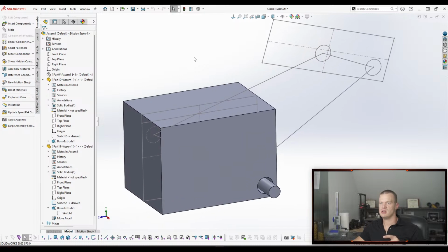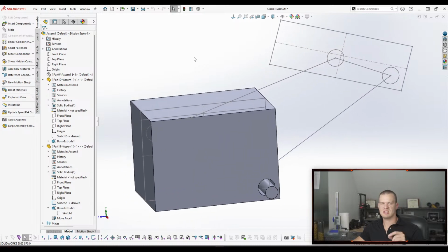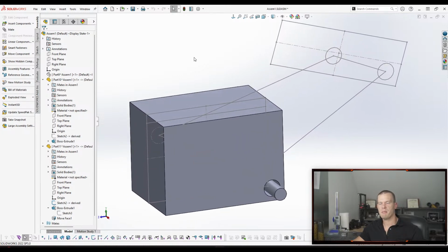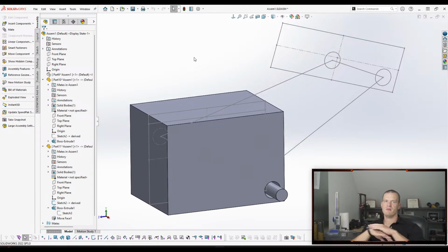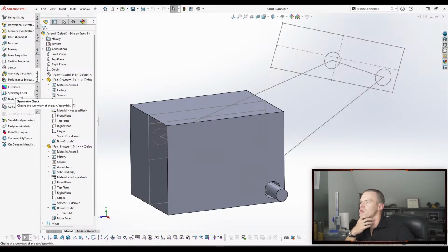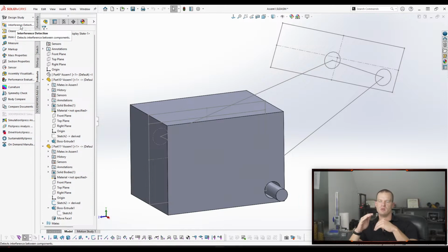In this situation, you don't see within the sketch that there is a gap, but what I sometimes like doing is I'll model everything line to line, and then I'll go back in and do where I know there's going to be gaps, because you can use interference detection. Where is it? You can use this interference detection to detect where two parts touch.